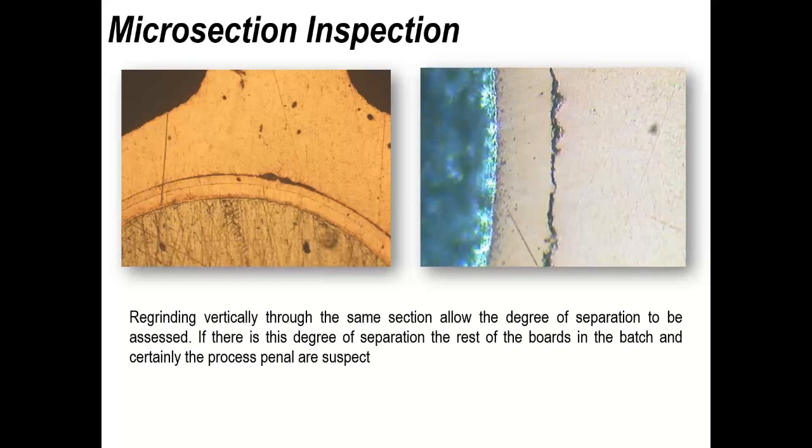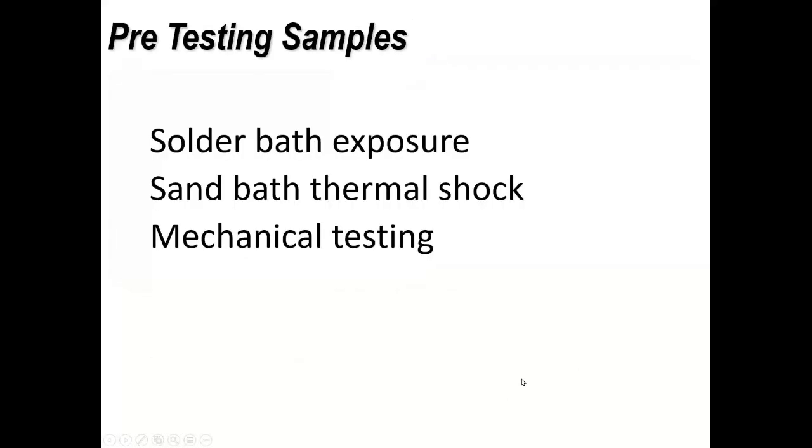So again, what we're trying to do is understand the type of defect, how widespread it is, how bad it is, as opposed to if it's just a simple issue that might well be met with IPC. If you look at IPC level 2, and certainly level 1, some separation between copper is acceptable, but the one on the right in this example clearly wouldn't be. So again, just a difference between specifications and criteria.